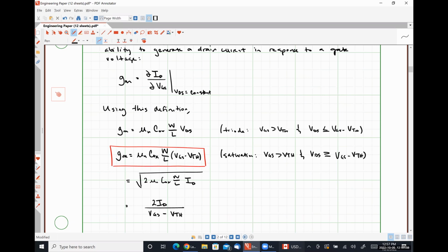So we're not throwing away a ton of information by calculating gm specifically using DC operating point values, and then only bringing the effects of channel length modulation into account when we're looking at things from a small signal amplifier perspective. In the long run, it's just going to mean less math. And we are just trying to figure out kind of how these things behave anyway, since this is all based on Boltzmann statistics. We never know exactly how the thing is going to behave to begin with. So this is giving us a good approximation of our behavior.